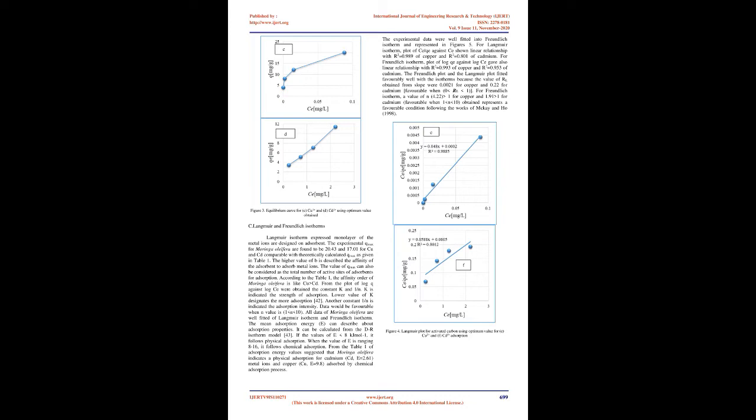3. Result and discussion. Characterization of activated carbon. 1. Surface morphology. Figure 1a shows the FESEM micrographs of the Moringa oleifera bark activated carbon before adsorption under 1000x magnification, while b is the micrograph of the activated carbon after adsorption under 30,000x magnification. There were many holes present on its surface. These holes were the available pores, where copper and cadmium molecules were to be captured from the wastewater solution.